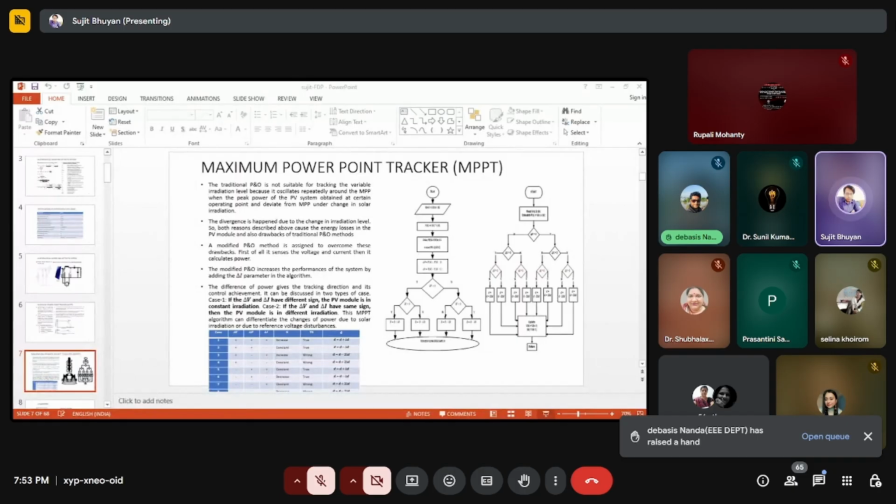So see here, previously in figure 1, the main figure, I have given you the battery unit. This battery unit has the buck boost converter, and the pulses are generated here. This is the control circuit, and by using this control circuit we are giving the pulses to both switches, T1 and T2. You can see VDC here, right? VDC is the DC link voltage, which is connected to the voltage source inverter. This voltage I have taken.